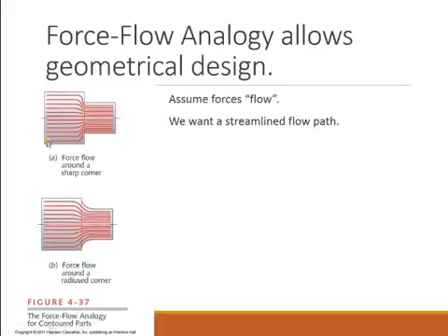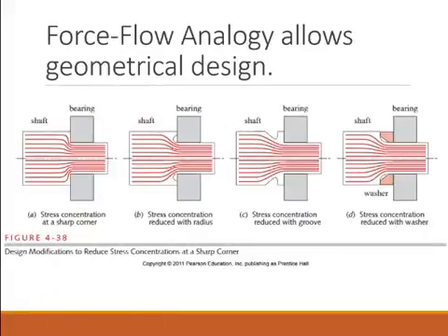And so if you have large places where there's a piling up of the fluid, where the force cannot flow fluidly, then you'll have an increase in stresses. So a radiused corner is much more smooth than a sharp corner, and we would expect the stress concentration for this to be much lower than for that. While it doesn't give us implicit numbers to use, it does give us some general guidelines to follow as we design our parts.